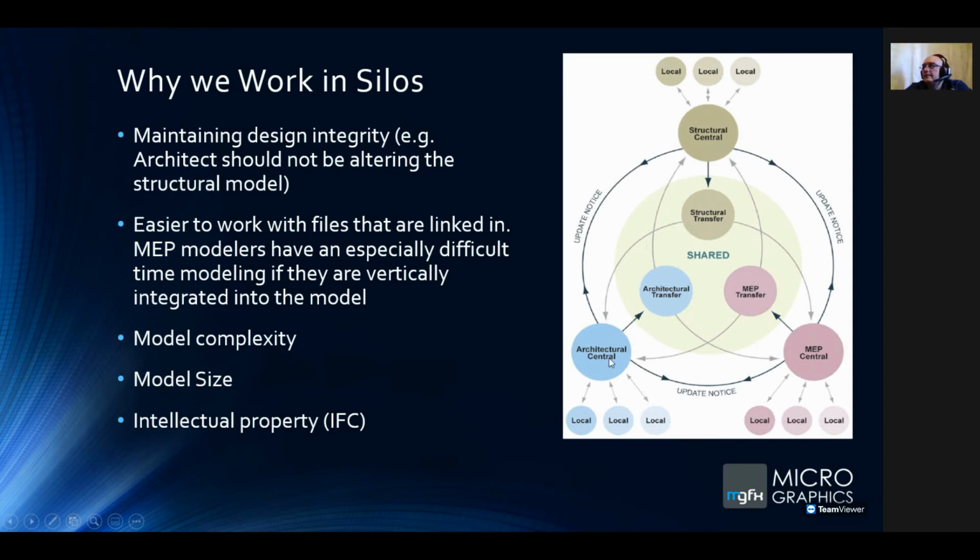Instead, what we like doing is to share the models into the common data environment. So once every 2 weeks or once every week, each one of us or all of us would share our model through a BIM manager into the common data environment, and then the other disciplines can link that model back into their model. So the MEP guy can then link in the latest architectural and structural shares, and the same thing with the architectural silo. They can share in the structural and the MEP shares, and that's how we do it.